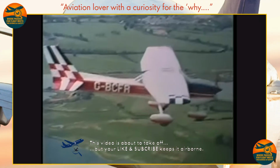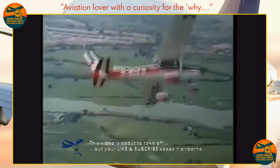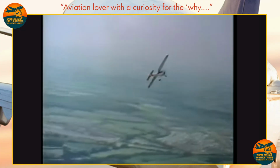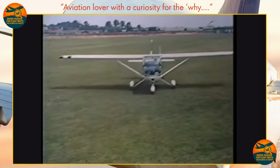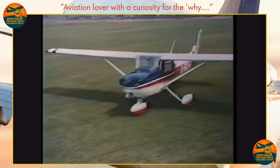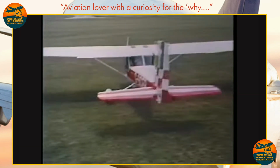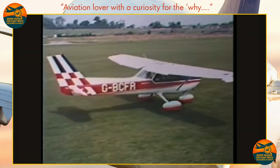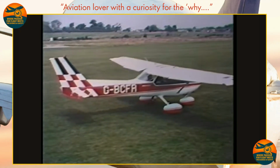The controls of an aeroplane enable us to maneuver it accurately and safely under all normal conditions of flight. Control is achieved by moving hinged surfaces on the trailing edges of the tail and the wingtips, the elevator attached to the tailplane, the rudder to the fin, and the ailerons to the wingtips. All of them operated by the controls in the cabin.